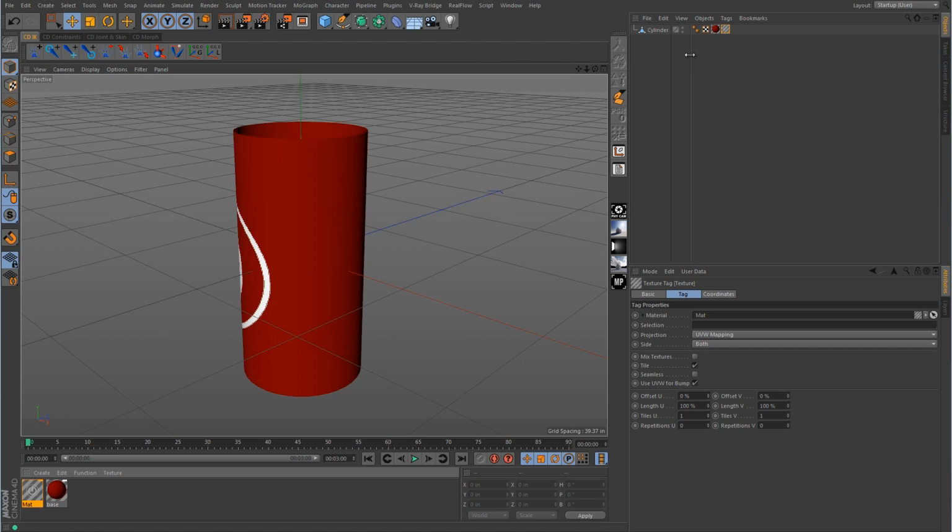Now keep in mind, and I think I've said this before, but I'll repeat it again, that the object manager over here on the right, you see there's two little panes here, window panes inside of this larger one. The left pane here with all of the objects in it, that is executed from top to bottom. But this pane over here on the right with the tags, this is executed from left to right. So over here it's top to bottom. Over here it is left to right.